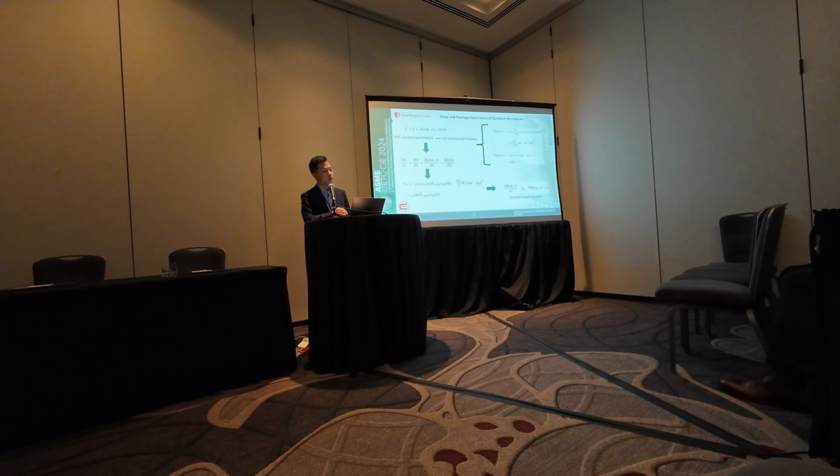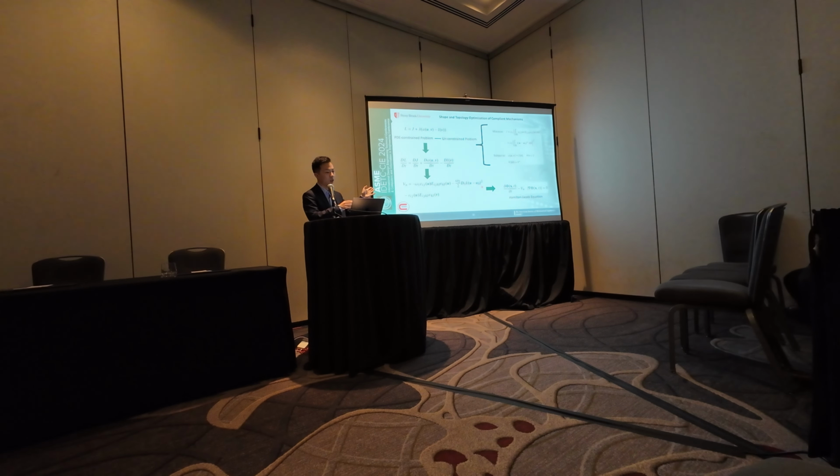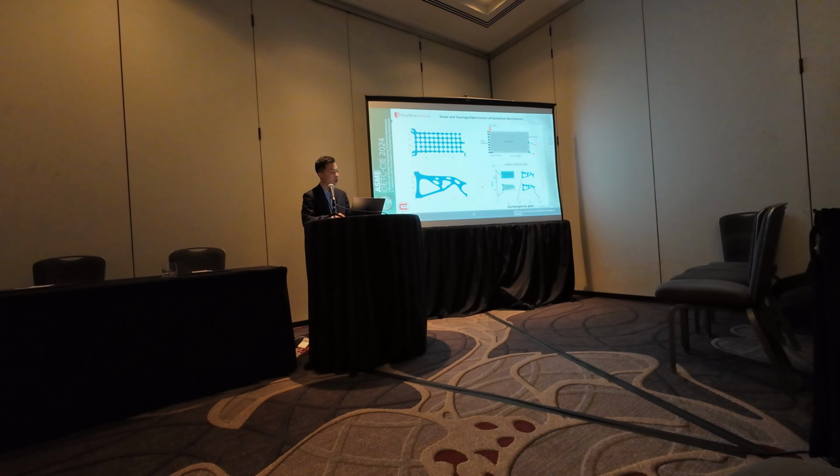And after that, we're going to take the total derivative of this Lagrange function, and then we're going to apply the adjoint variable method. After that, we can get the final design velocity, which is shown here, and we're going to put it back into our Hamilton-Jacobi equation, because the evolution of the boundary dynamics is governed by the Hamilton-Jacobi equation. Okay, so here's our design example.